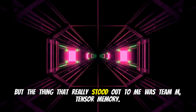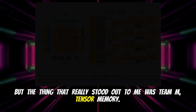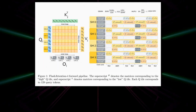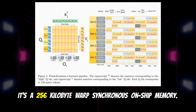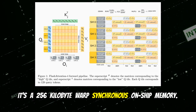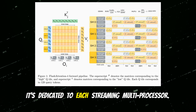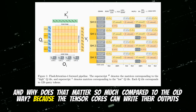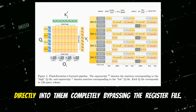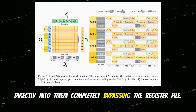But the thing that really stood out to me was TMEM, Tensor Memory. Oh, TMEM is huge. It's essentially an architecture-defining feature for Blackwell. It's a 256 kilobyte warp synchronous on-chip memory that's dedicated to each streaming multiprocessor. And why does that matter so much compared to the old way? Because the tensor cores can write their outputs directly into TMEM, completely bypassing the register file.